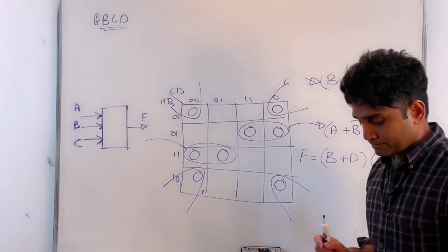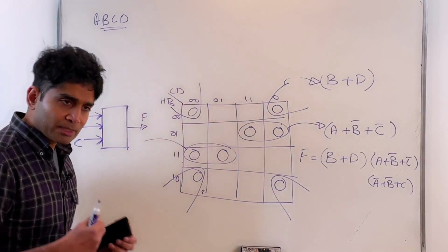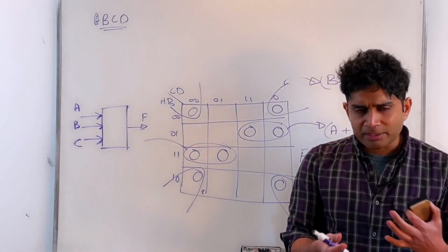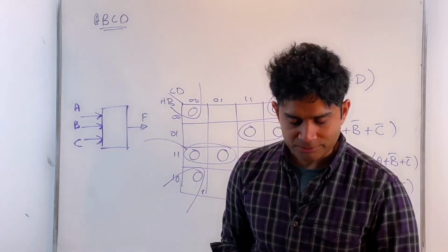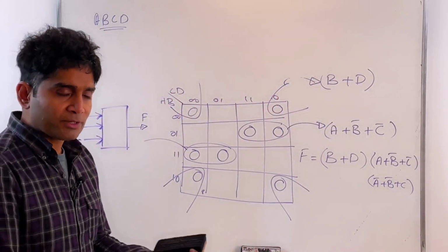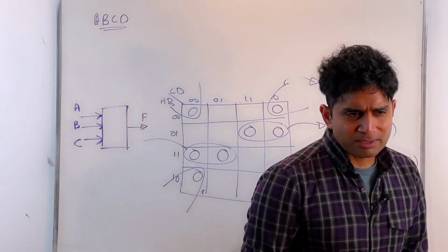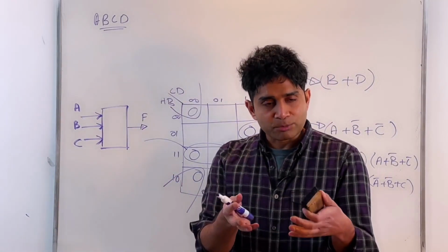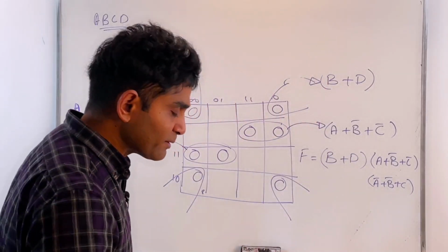Now that's one possibility. The other possibility is that some of the input combinations never occur at all. So I've designed my system so that some particular input combinations are never going to appear in an actual situation. Now, for those instances, also, obviously, I don't care about the function. When I'm designing my circuit that corresponds to that function, I don't have to care what my function should output for those input combinations, because they are not going to occur anyway, right? So 2 different possibilities here.